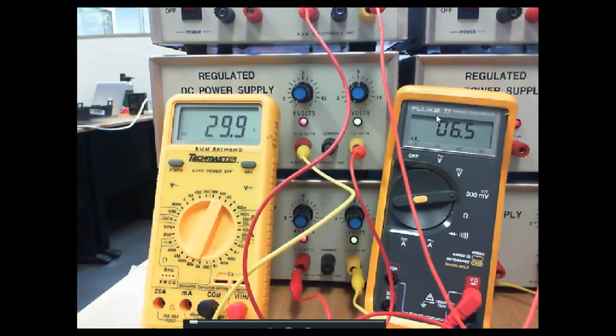So this is our computed current. Y'all got a calculator? I don't. Well, I do have a calculator. 1 million. We're protecting this thing with a 1 meg ohm resistor. So if I had a 100 ohm resistor out there, as soon as this thing broke over, this diode would be gone. But what we're doing is we're using that 1 meg ohm resistor. First, it makes it easy to calculate current. So once you figure this first one, guys, you probably don't have to do the math anymore.